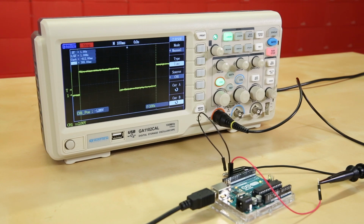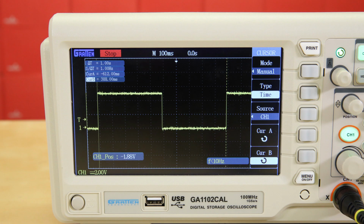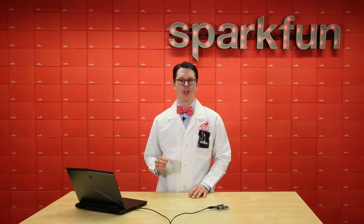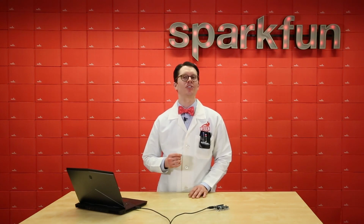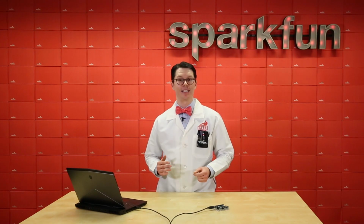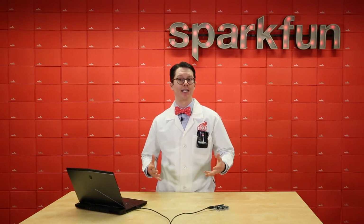Just to show you that we really are blinking at a rate of 1 Hertz, I've set up this oscilloscope, and as you can see, it's about 1 second measured from one rising edge to the next. Using timer interrupts is great for when you need to run pieces of code at exact intervals. We can make this even slightly more efficient by using the clear timer on compare mode. All this does is tell the hardware to automatically reset the timer back to 0 whenever a compare match interrupt happens.